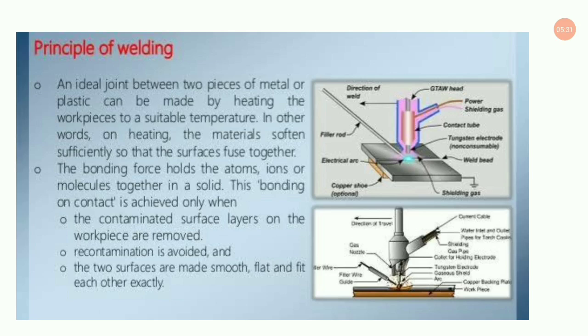Okay, so it is generally believed that electrons liberated from the cathode move toward the anode and are accelerated in their movement. When they strike the anode at high velocity, a large amount of heat is generated. Also, when the electrons are moving through the air gap between the electrodes, also called the arc column, they collide with ions in the ionized gas column between the electrodes. The positively charged ions moving from the anode impinge on the cathode, thus liberating heat.